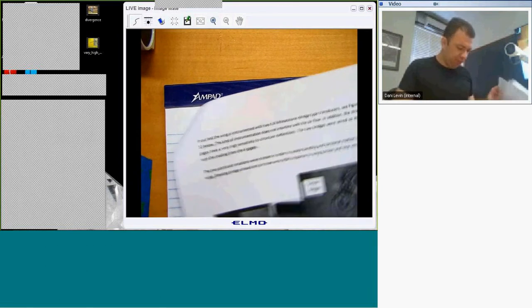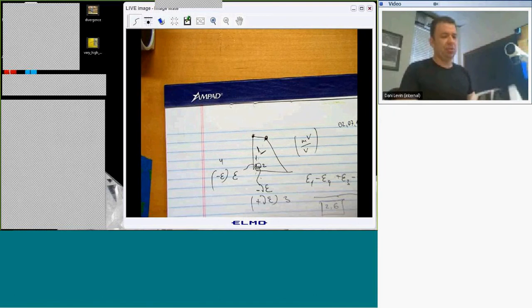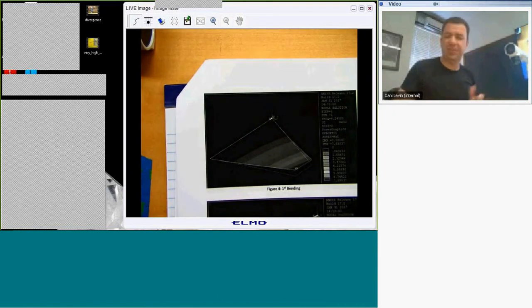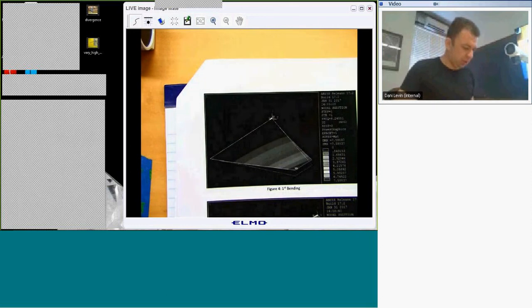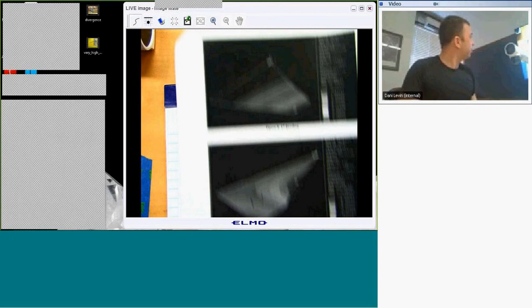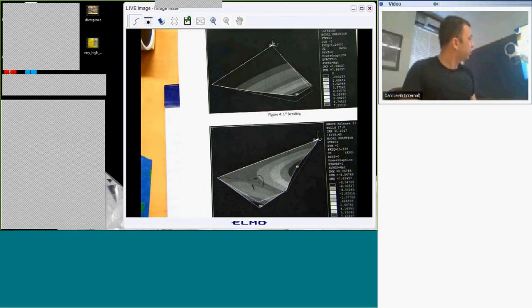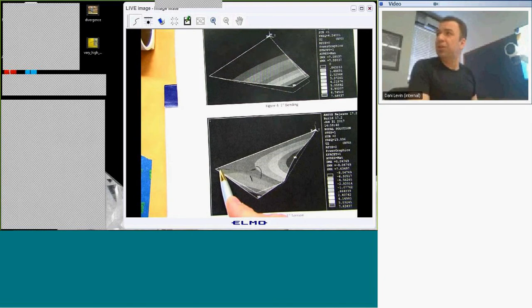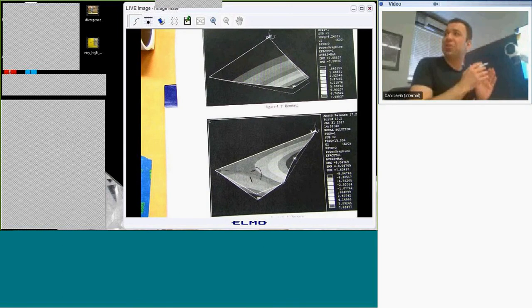Because wherever you instrument something, your goal is to go beyond the noise level. So let's see, for example, here this is the torsion mode, okay? And here there are no actual readings. Okay, you don't want to put your instrument there to measure this mode.